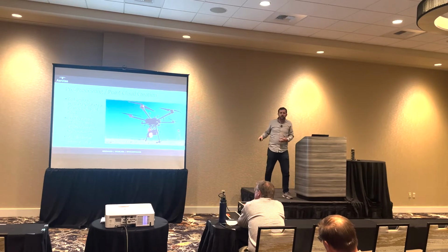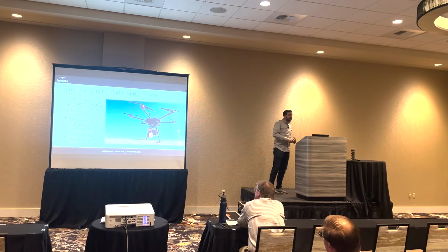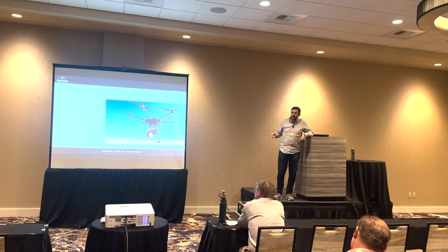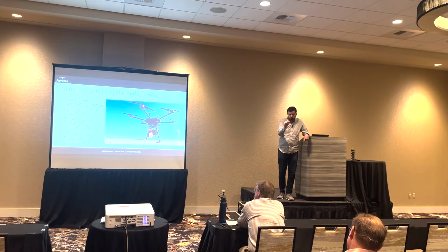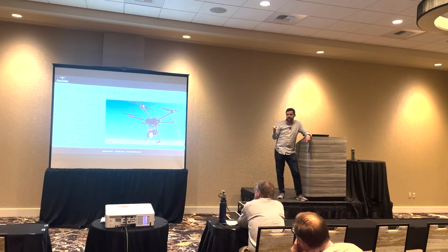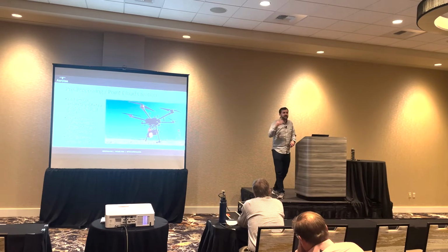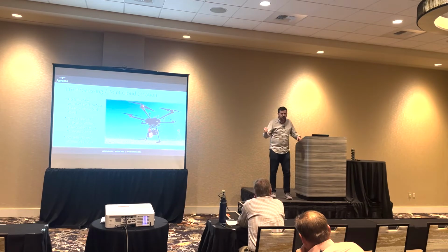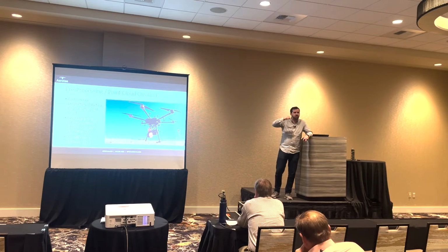So, this is where you go from raw, typically proprietary data into a clean, useful point cloud. Because when the data comes out of the LiDAR sensor itself, purely that LiDAR unit is just sending a beam back and measuring the distance. And so what it records is the intensity and the distance and the time. And that's it. It's not a point cloud at all, at least from a data architecture. It's just raw data. The problem is that LiDAR sensor is moving around. It's on a gimbal, it's on a moving drone.